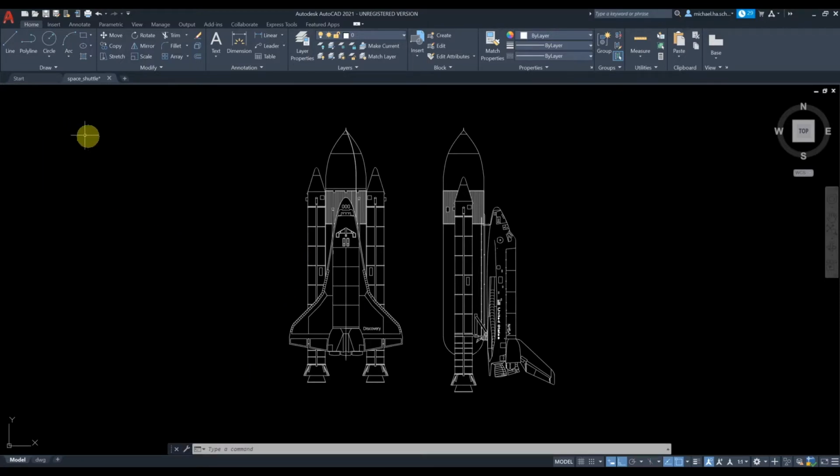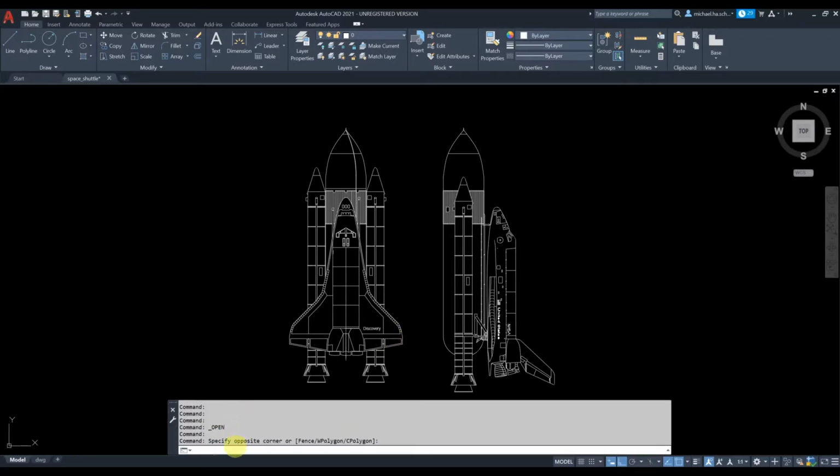And there were icons. However, the very old users of AutoCAD were very comfortable using just the command bar. For instance, typing L, press enter, that invokes the line command. You single left click a start point, second, third, and so forth.